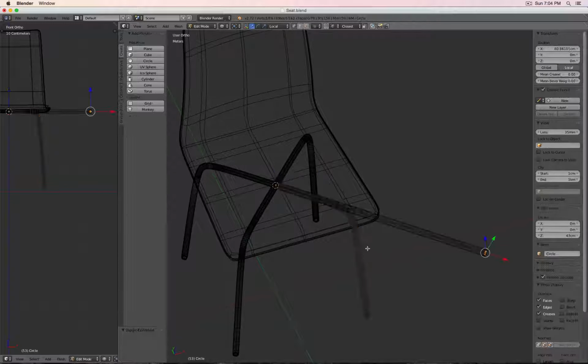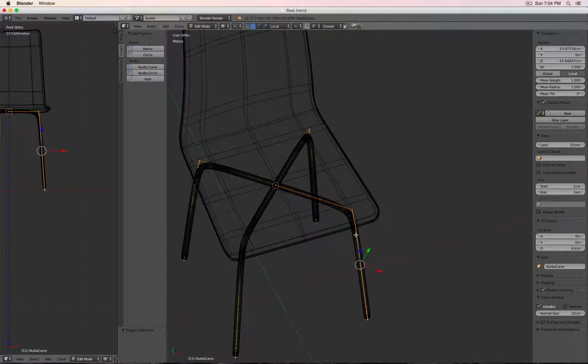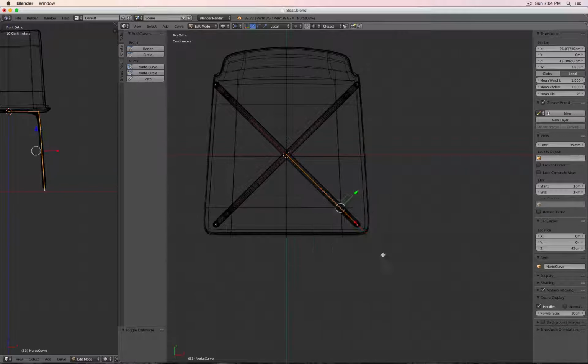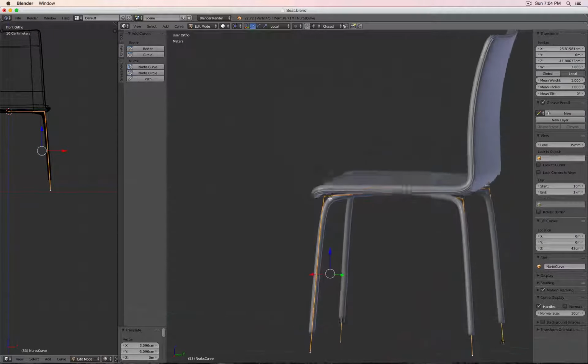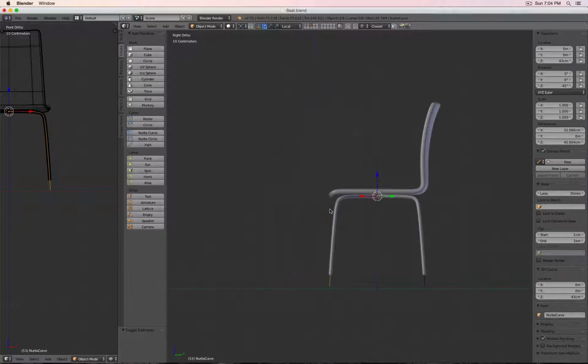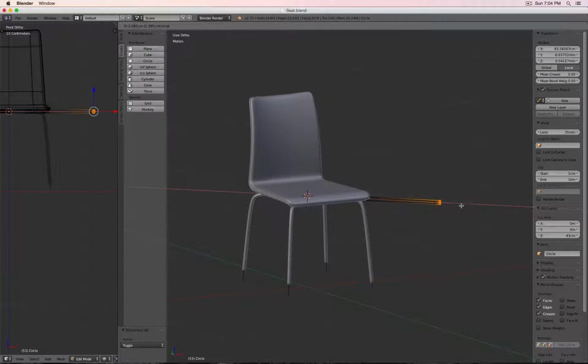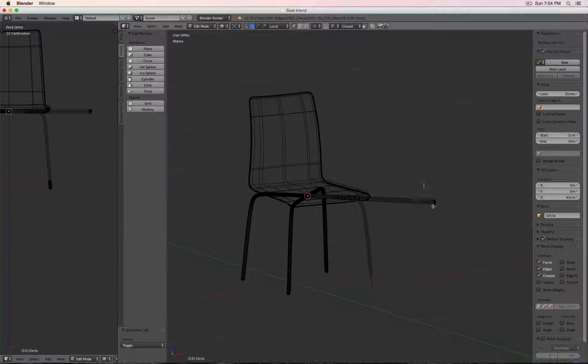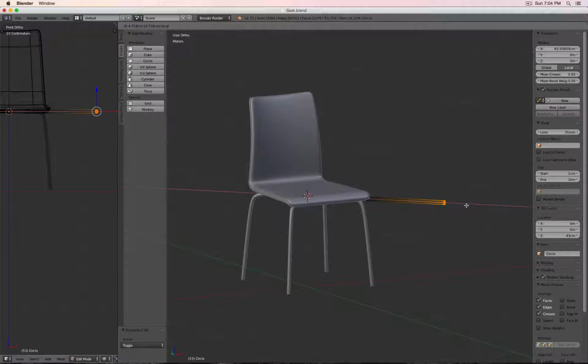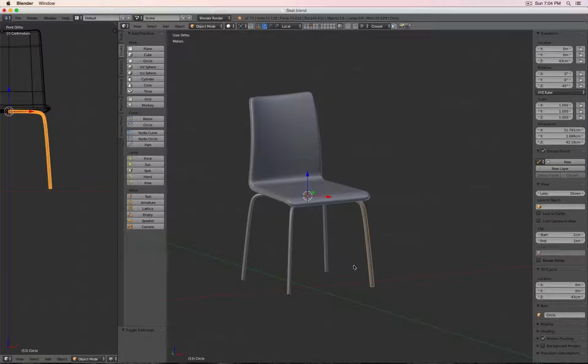and then first I can select this NURBS curve. You see I'm inside local mode, and I simply move all these vertices along the local direction, and that shows us now our pipe is too short. I select one of those geometry parts, and then along local space simply extend it, leave edit mode. Of course I have to select all there, zip, and now all legs are updated.